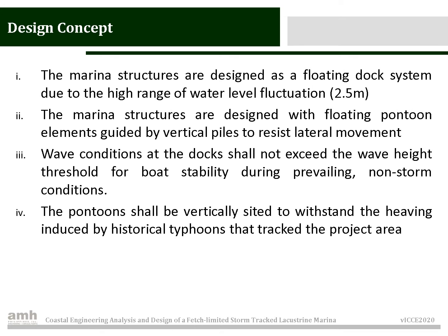The marina structures are designed as a floating dock system instead of a fixed structure due to the high range of water level fluctuation of approximately 2.5 meters. The floating pontoon elements are designed to be guided by vertical piles to resist lateral movement, and the wave conditions at the dock shall not exceed the wave height threshold for boat stability during prevailing conditions. The pontoon shall be vertically sized to withstand the heaving induced by historical typhoons that tracked the project area.